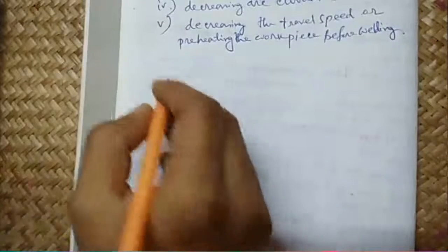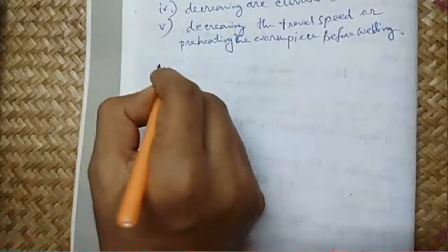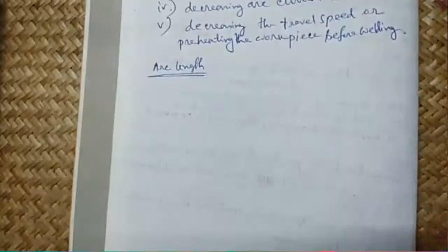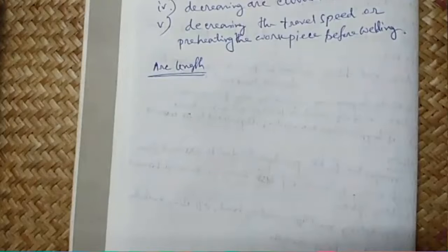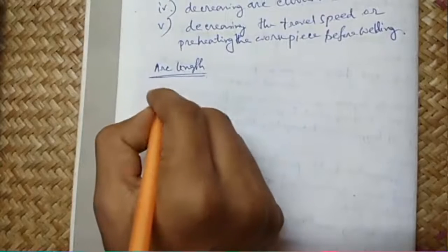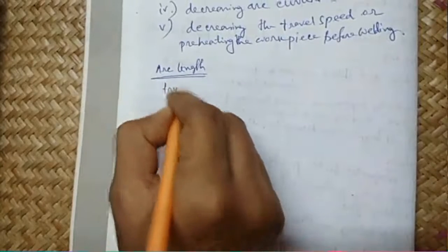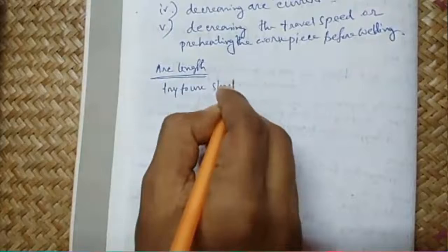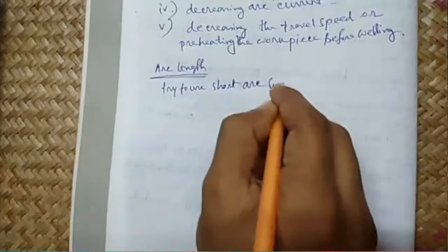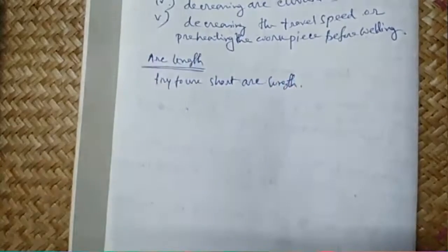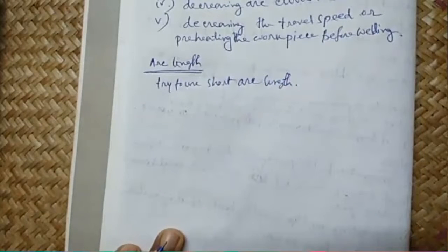Okay. Our next topic is arc length, which is very, very important. We always have to try to use short arc length. We will not use longer arc length. We use short arc lengths.